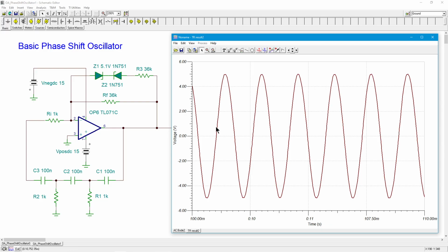All right, so when the signal's getting up like here, that's when these Zeners start to turn on. And it's getting just a little bit of current through here. You're putting this whole resistance, whatever the Zener resistance works out to be plus R3, effectively in parallel with this RF, just enough to bring this down to give you the gain that you need, right?